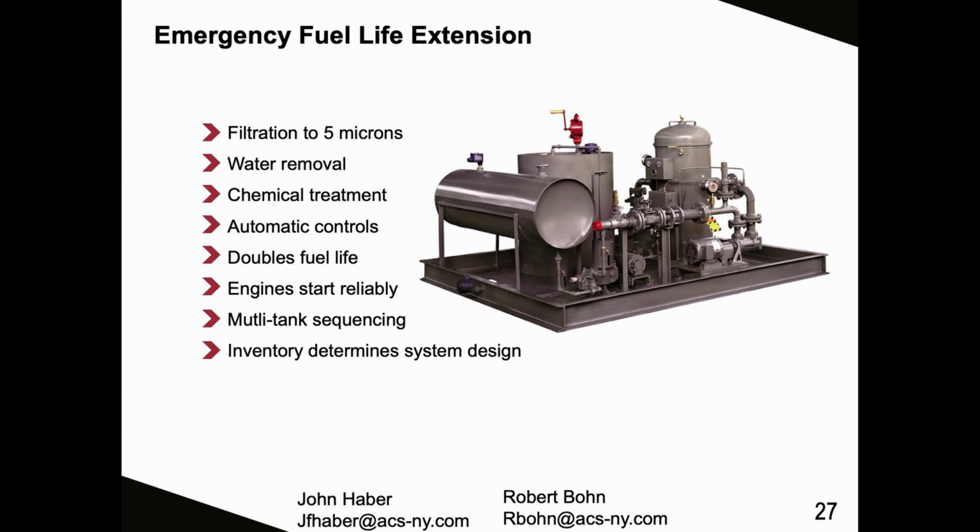On this next slide here, we have a skid-mounted fuel oil filtration system. This is for your larger applications, a couple large tanks. Again, we can filter down to 5 micron, get your water and sludge removal out. It can also do chemical treatment, automatic PLC controls for automatically sequencing your filtration system when your units are down and your tanks are just sitting for a certain period of time.